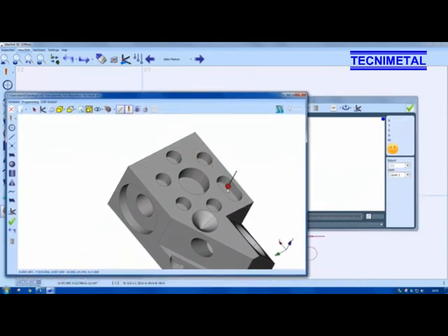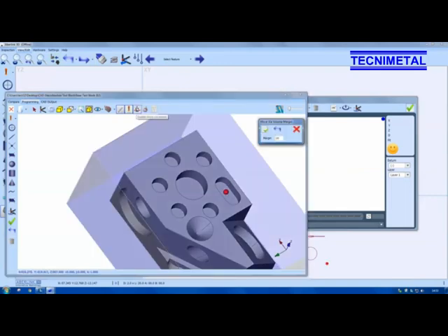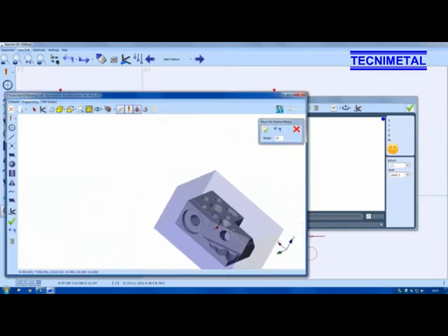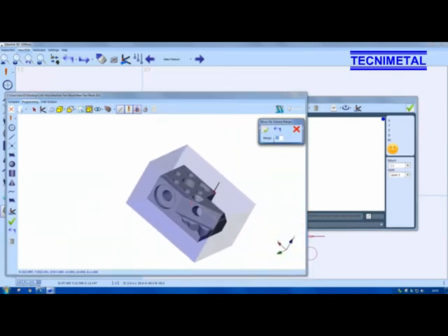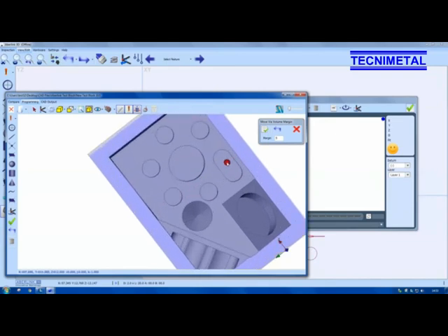So to do this, we take a point inside on the surface and switch on this icon here, which places a cube around the CAD model. So this can act as a safe value. I can adjust the margin. Okay, so now it's switched on. I'm actually going to probe the edge of the volume. Move across,